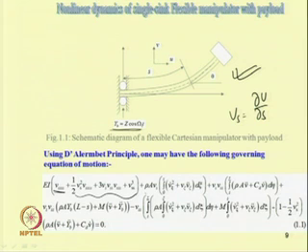Then one can write ρA V_s ∫₀ˢ (V_ζ dot squared plus V_ζ V_ζ double dot) dζ plus V_s V_ss ∫ₛᴸ ρA V double dot plus C d. So, this is due to damping, and this part ρA V double dot is due to inertia. So, this is the inertia force, this is the damping force.